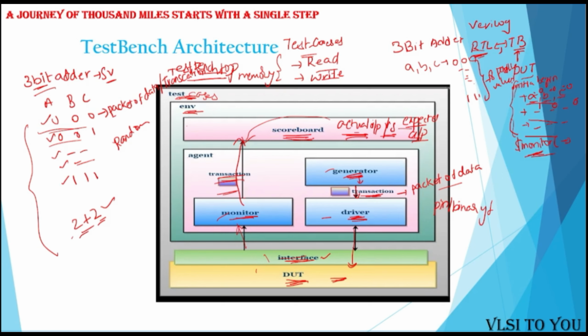Now you may get a doubt: in Verilog, you don't need all these things for a simple adder. This is very huge compared to Verilog, and for a simple adder, do we need to do this much? No. If you have limited your idea to only add, subtract and counters or something, you don't need this big SystemVerilog structure to check all these things.